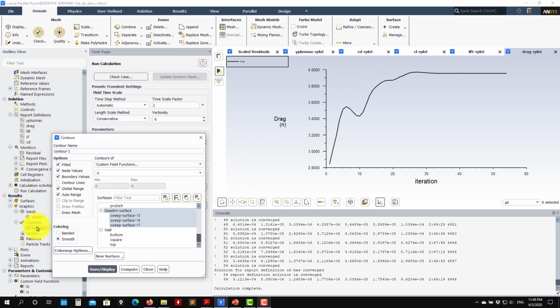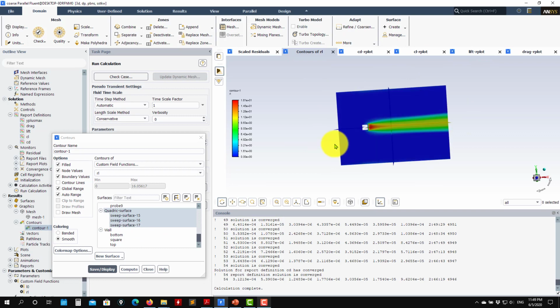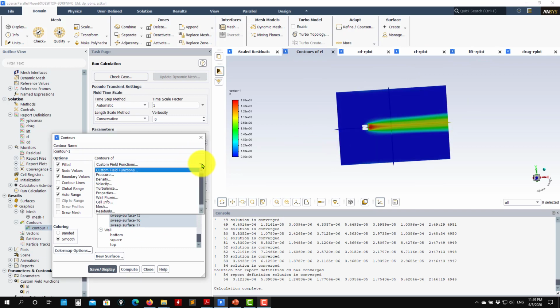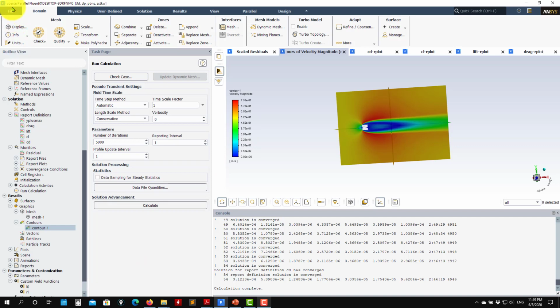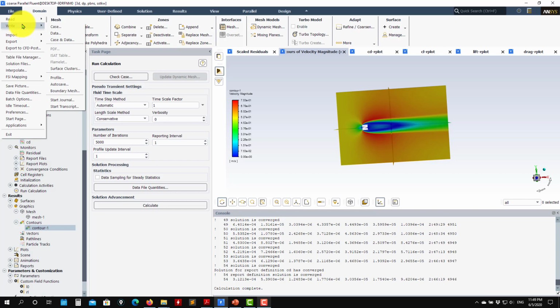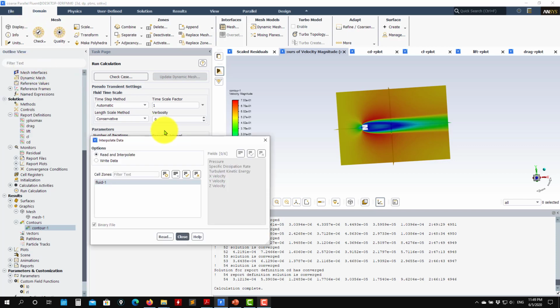With the coupled solver, we know that SIMPLE will have different behavior, and then you can start and plot and do all the post-processing that we have done so far. Compute the integral length scales, plot velocity, whatever you want. Then also save your interpolation files, and then you interpolate this one in the steady cases and keep going. At this point we are almost ready to start the LES simulation.